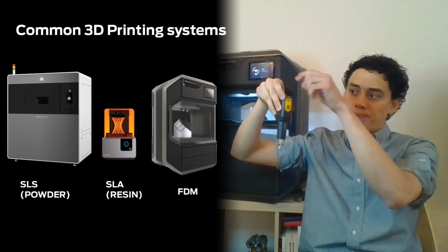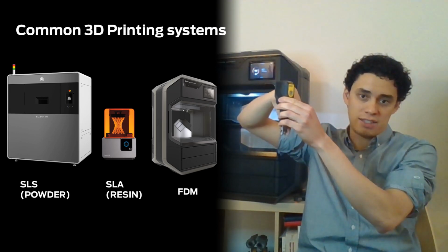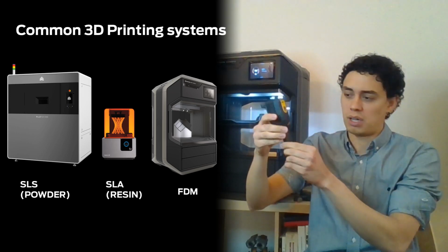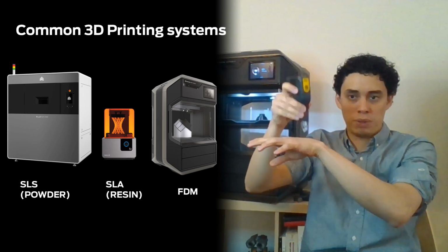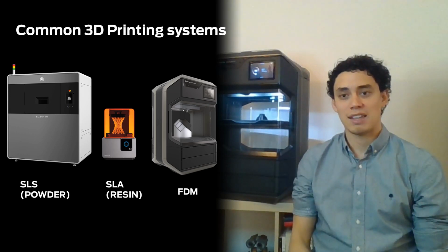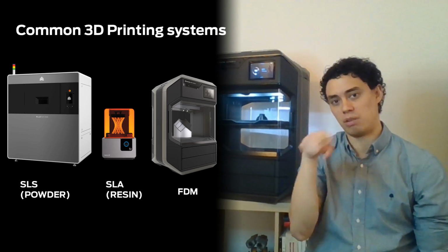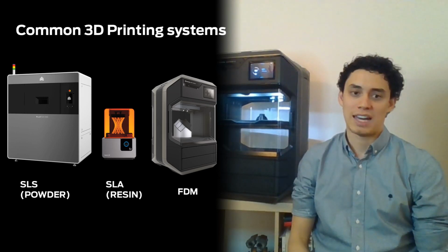The method actually liquefies the plastic as it goes through, and that's true for all of the MakerBot extruders. It liquefies the plastic and then deposits it in place, right, where you're building the part. With an SLS, an SLA system, there's basically a laser pointer that's drawing that shape.